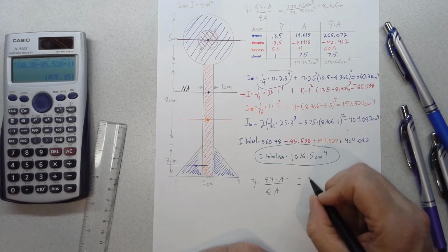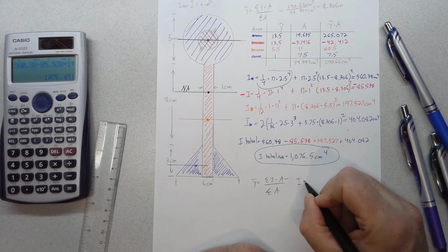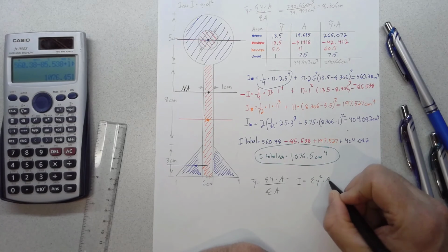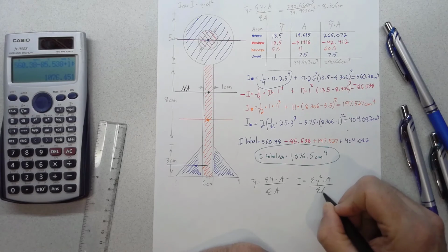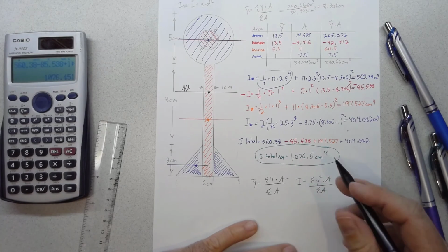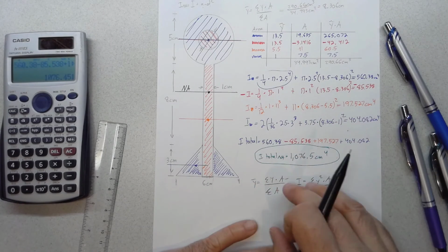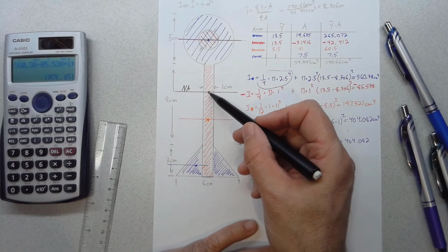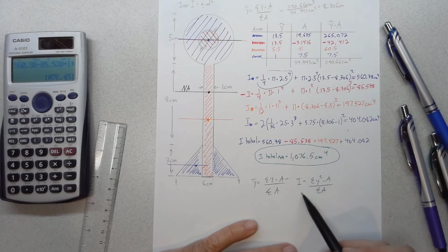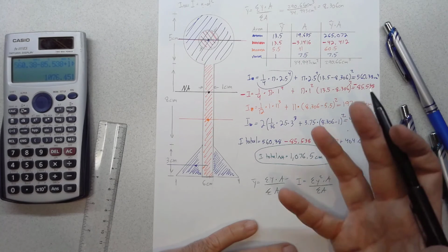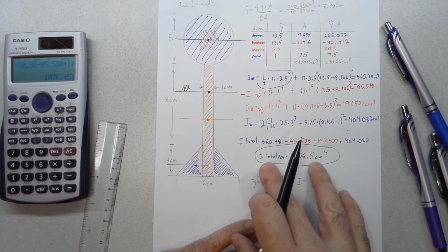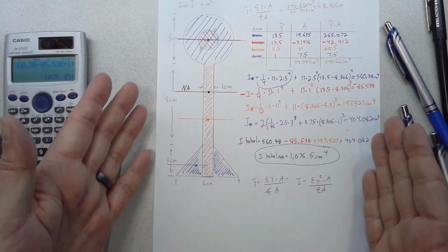I is what we call the second moment area. So it's really the sum of y squared times the area over the sum of the areas. So kind of a very similar concept, except this one has a physical representation, right? That's the balance point of the shape. This one is a geometric property, but not a physical property that you can visualize or measure. Okay, so that's our total. So we've shown how to do a complicated shape like this.